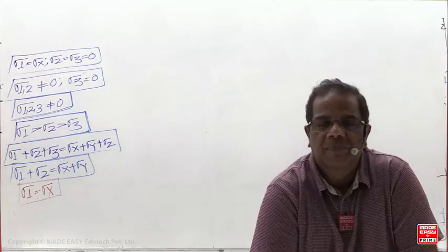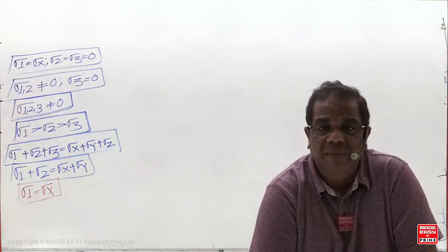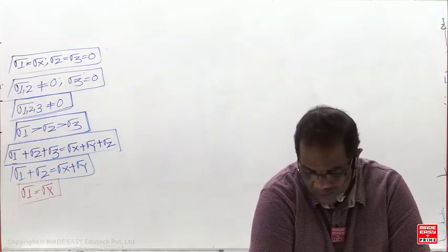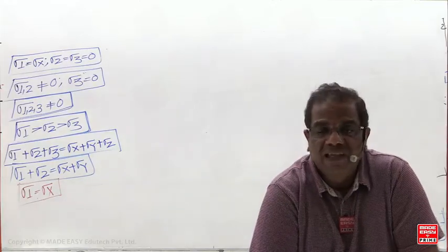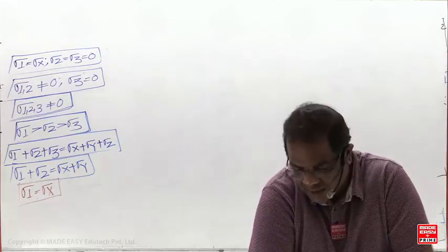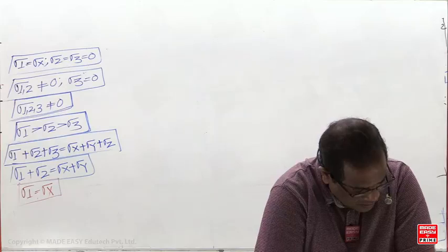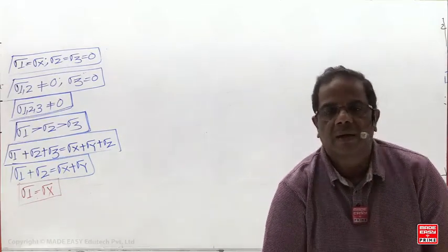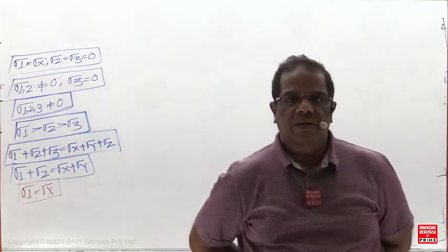I am going to repeat it. Normal stress on tau max plane is equal to 0 when sigma x plus sigma y is 0. Then tau max planes are also known as planes of pure shear stress.